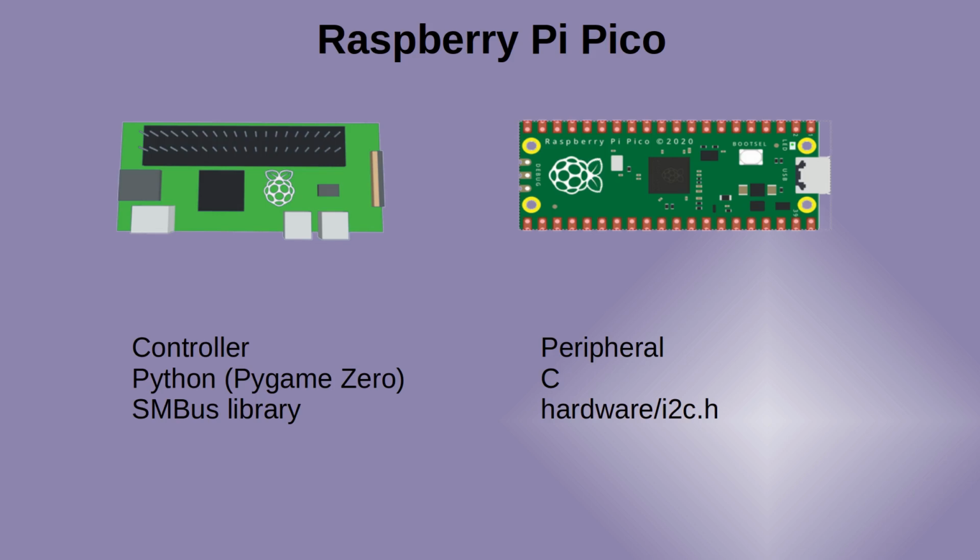I'll still be using Python on the Raspberry Pi, as that allows me to create a simple GUI using Pygame Zero, although this introduces a bit of a problem with incompatible implementations. The Python library I used is known as the SMBus, which implements System Management Bus. This is based upon I2C, but uses different messaging. They do work together, but I wasn't able to send multiple data blocks, and I did implement a little trick to be able to send data 16 bits at a time.